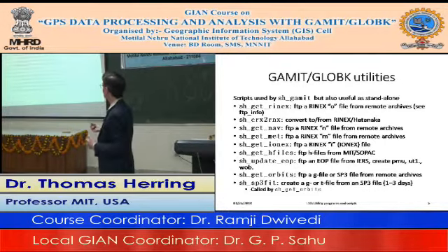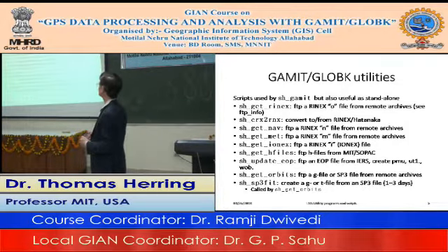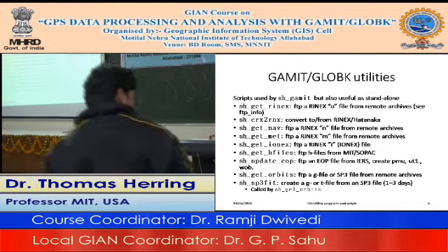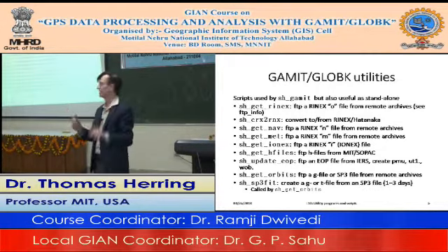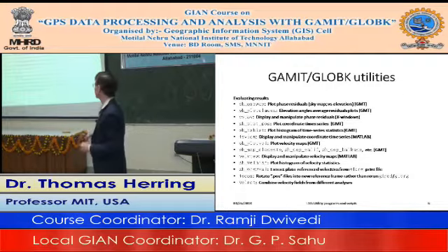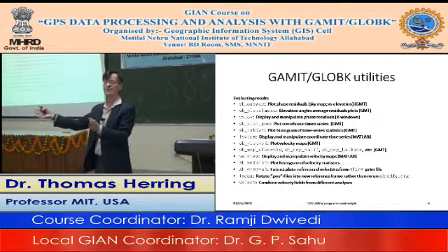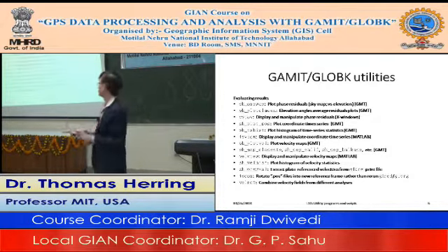Now, there are lots of other GAMIT/GLOBK utilities. We've looked at some of these, but others we have not yet. SH oneway we looked at when we were plotting the phase residuals, and that's very useful to see the quality of the data. We also looked at SHPlotElMean, which allows you to compare many days of data to see how the phase residuals are changing with time.